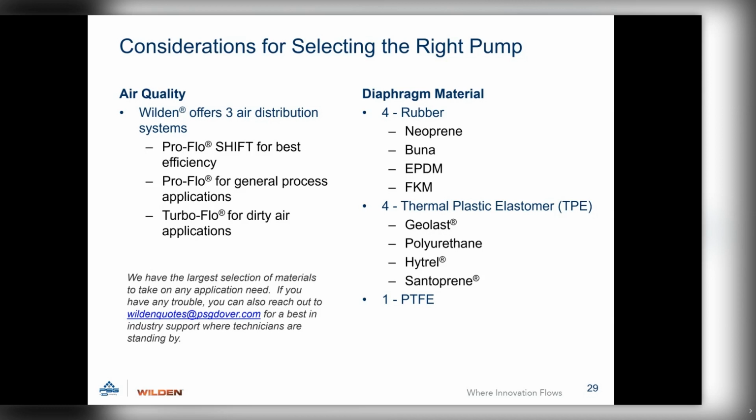And then finally, our PTFE, which is a PTFE overlay, which requires a backup diaphragm. So basically, you would select a backup diaphragm that's also compatible, but the overlay on that diaphragm is going to be made of PTFE. And those are for the applications where whatever's being pumped is very aggressive or proprietary, and you don't know what the materials of construction or the materials being pumped are. You would select PTFE.